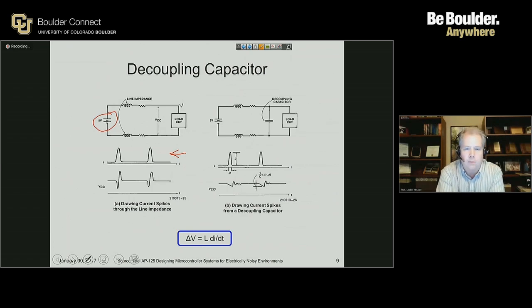And when you get these bursts of current, you get an impact on your voltage rail. What you see in the bottom diagram are these perturbations or deltas that occur on the VCC rail because you're taking these large draws of current over a short period of time.